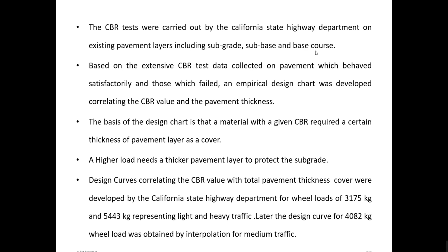subbase, and base course. On what layers is the CBR test going to be adopted? It is adopted for the three layers: either subgrade, subbase, or else base course. So, what is this CBR going to indicate to us? Based on the value of the CBR test, we will be able to conclude what should be the thickness of a flexible pavement that has to be provided for the considered pavement. Either it might be a flexible pavement or else a bituminous concrete pavement.